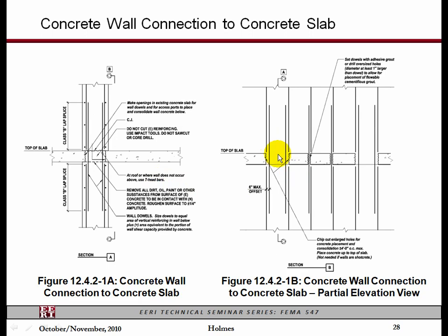So what we often do is actually make intermittent cuts. So you make a complete cut hole here to get 4 rebars through. Here you just put a single rebar through the existing slab and then alternate this, and you in fact end up eliminating shoring in many cases and still get all of your forces through.